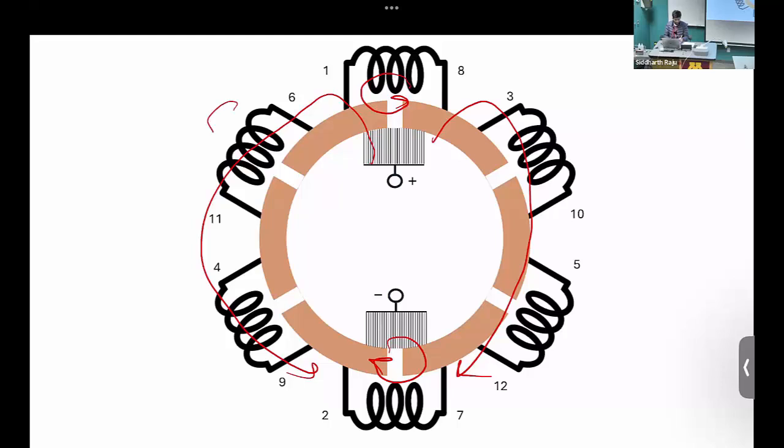But if you look at the EMF, only 2 coils are contributing to the EMF that you measure across the terminal, right? So the problem is, if you look at our EMF profile, previously it was like this. During the short, 1 coil got dropped, so the EMF would drop at that point. And then it'll again be flat and then short. So every time this commutator action happens, the EMF will start to dip a little bit, right? And that also means the torque will also drop. The coil that's producing the torque is also reducing.